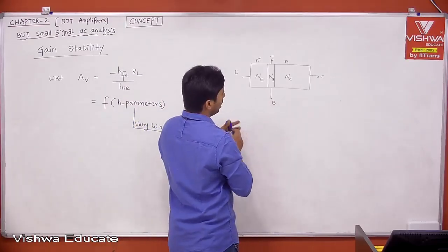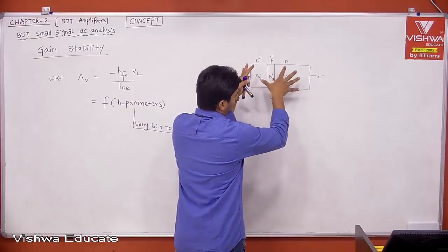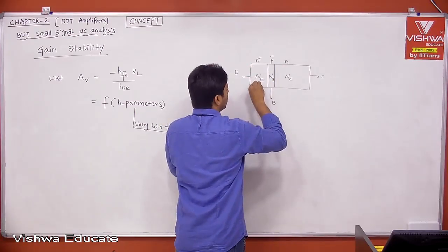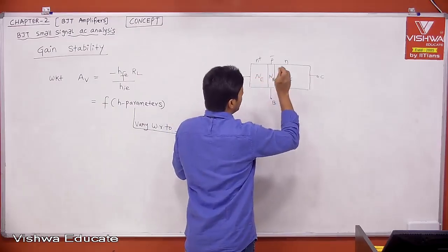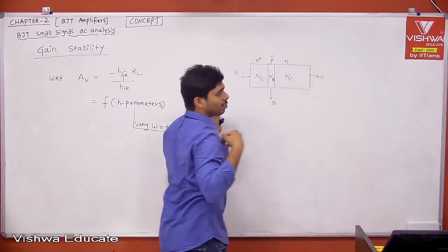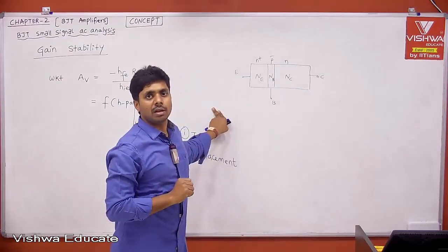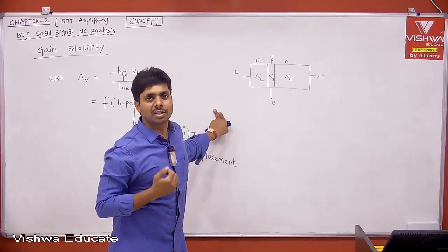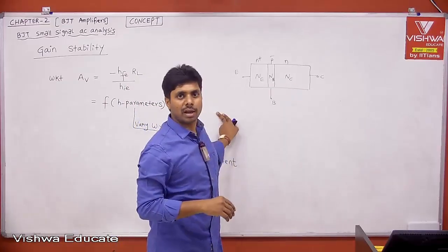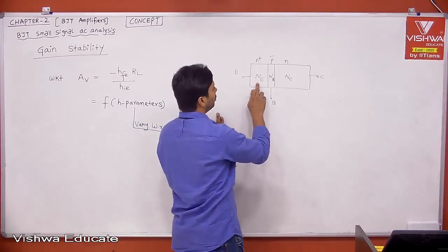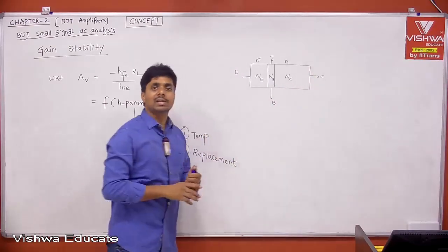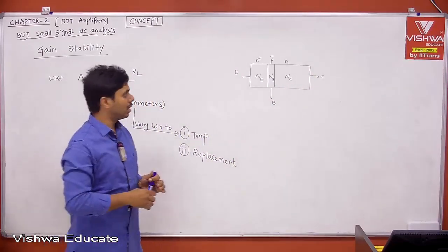Therefore, when I say I want the same structure or same base width, same emitter doping concentration, same base doping concentration, same collector doping concentration for all the transistors. Let us say I want identical transistors, right? That is my requirement as a designer. But remember, because of fabrication variations, you will not see the same doping concentration for identical transistors. Let me tell you the reason.